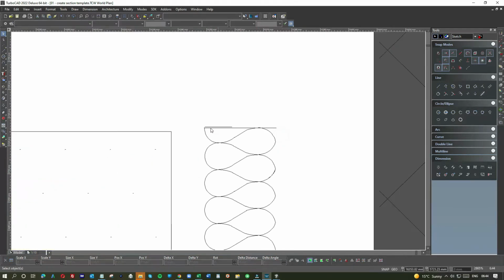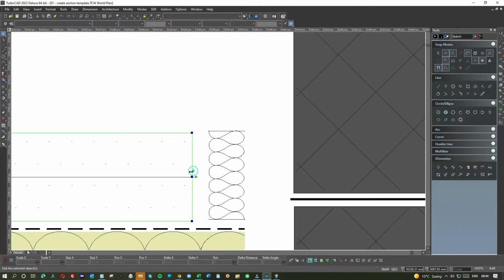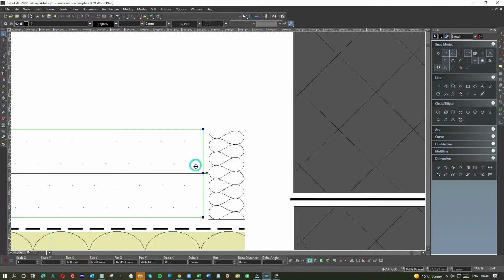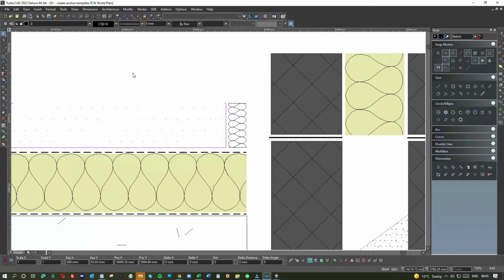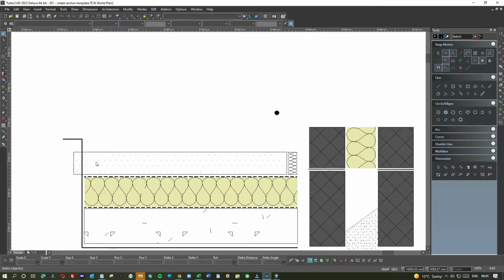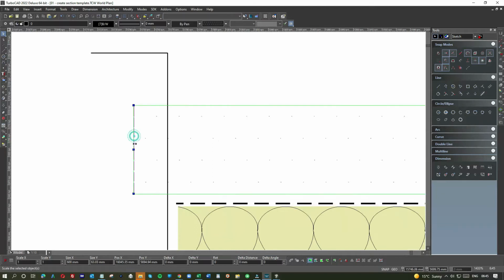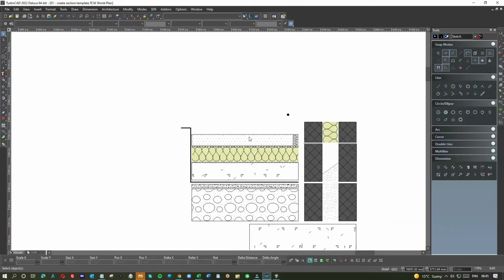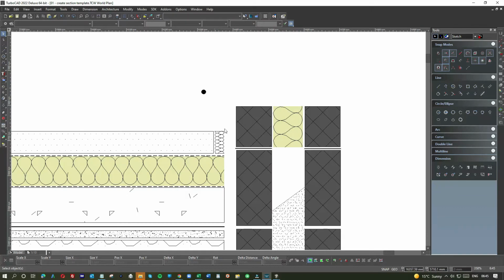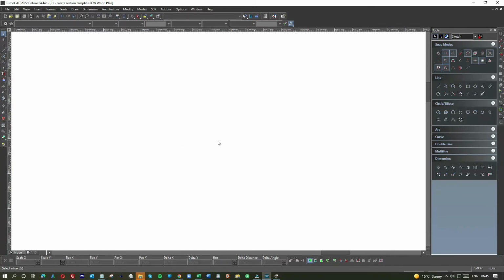And let me get a look at this insulation here. So yeah, it's like a barrier insulation, but very important. Again, it's important that I illustrate it correctly. A lot of the builders don't even know about that, and as a result your build is compromised before you do anything. Right, so that's a finished floor. And where the finished concrete floor abuts or meets up to the wall, there should always be a little bit of insulation here, and basically the skirting goes on top of that. So you'll see what I mean.